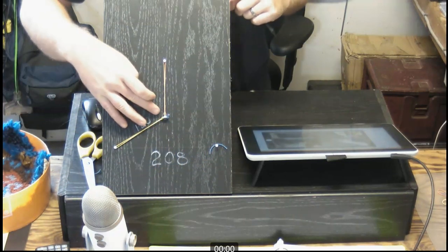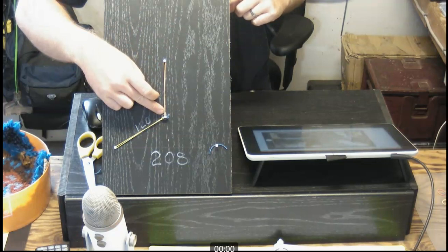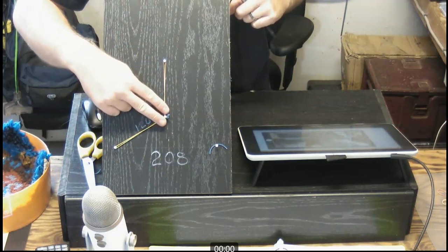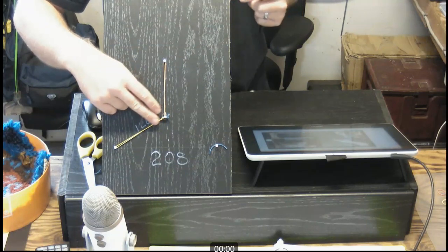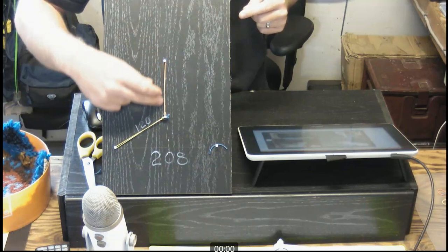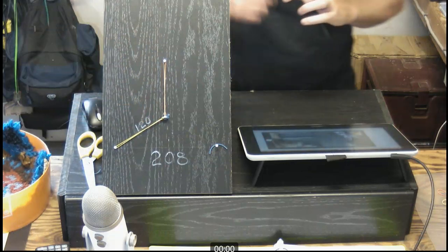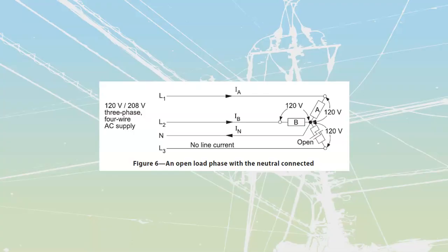The other thing that I'm going to note is that because I've got my neutral connected, if I would stick an ammeter around my neutral line itself, now I'm going to have current coming back along that neutral, because that neutral is no longer truly a neutral. It has now turned into a common because it's only got 2 lines that are tied to it. We see that inside of this one over here.